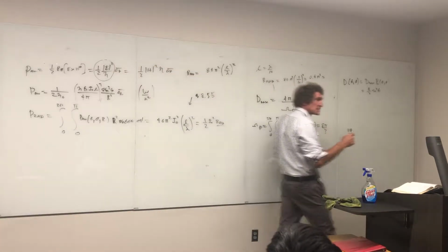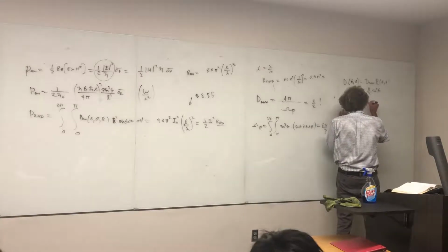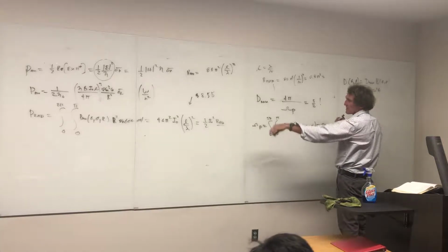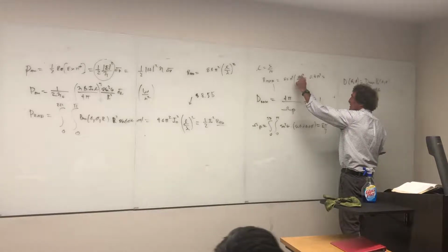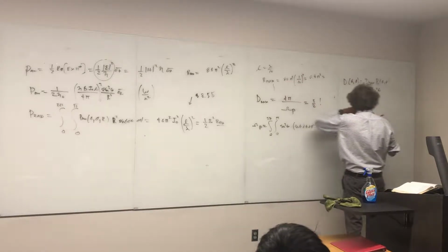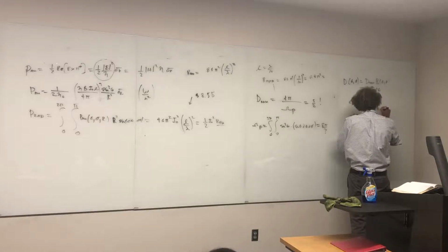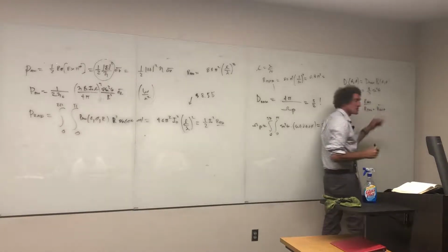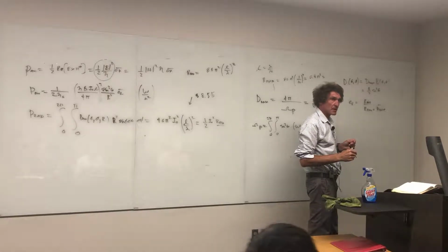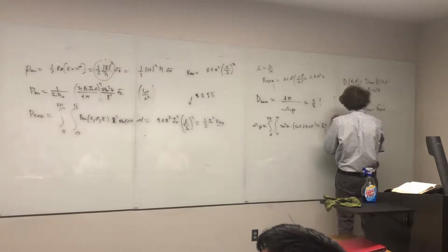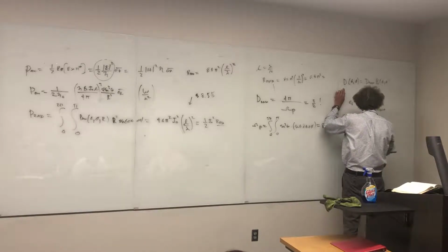Anyway, what you'd find is this. You would get the efficiency equal to simply R radiation, which we have as this, R radiation is 80 pi squared times length over lambda squared, right? And it would be R radiation over R radiation plus R dissipation. That would be the AC resistance of the antenna. Clear on this, everyone? I'm going through the whole thing with you. Make sure you get it. Once I have that, I can get the gain, and the gain is just going to be the efficiency, right, times the directivity as a function of theta and phi.